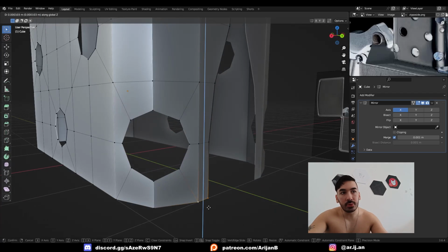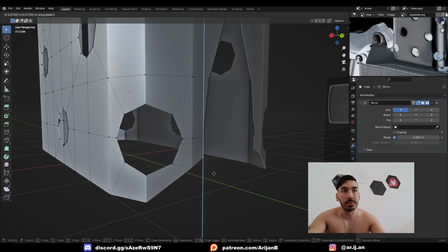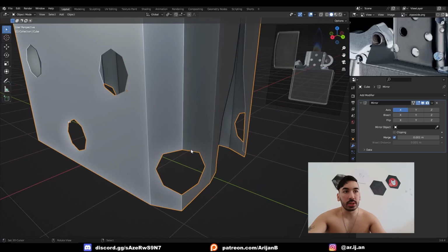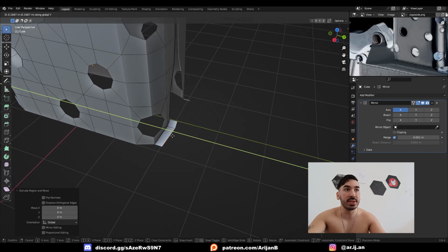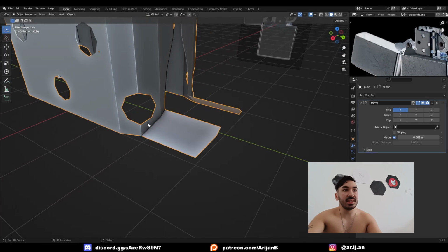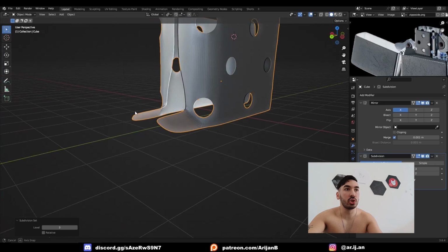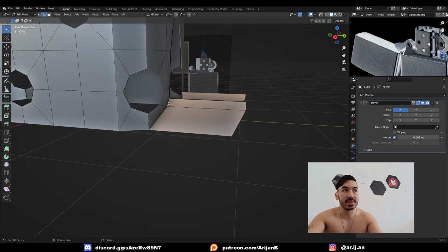Now I'm going to take these vertices from the bottom and lift them up, and I'll take the corner vertex and lift it up a little bit further. This way the faces stay perfectly flat, so the topology stays clean, but I can take these two edges and extrude out this little part, which holds this little thing which keeps the lid open. And obviously this is supposed to be smoother, and once we add a subdivision surface modifier, this is going to get a bit more round. So for now it's just going to be this way. This is the low poly version.